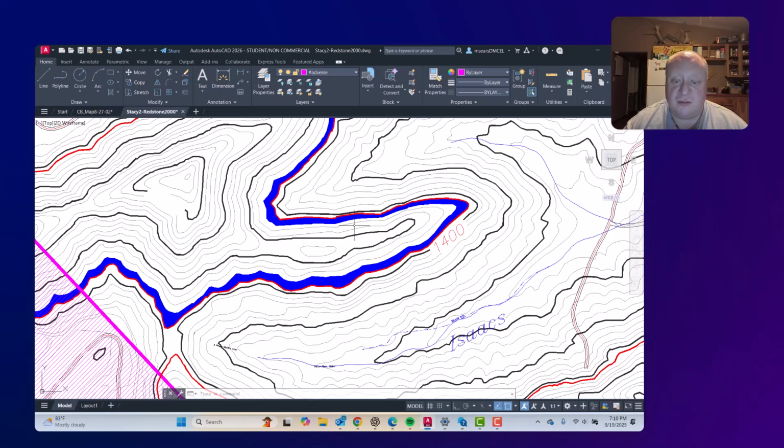And then once you take off in one of these directions, there'll be places behind you to start storing your overburden, right? Using the haulback method, where you'll open up a pit, for example, and then you'll take that material back up here onto the high wall, fill up an empty pit, obviously leaving space for high wall mining as well. So you have to have some space opened up to do all of that at once, but you'll be dumping back, at some point, right? Because you're going to refill this, back to the approximate original contour.